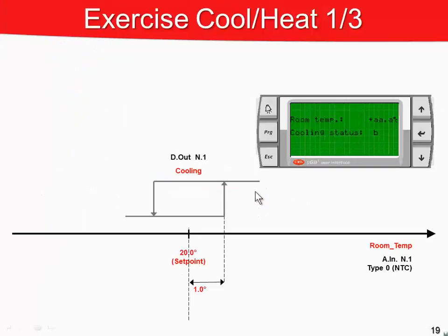These are the requirement specifications of the first exercise. There are only two operating parameters, the set point and the differential. The set point defines the central value of the stage, while the differential defines the half of the stage.